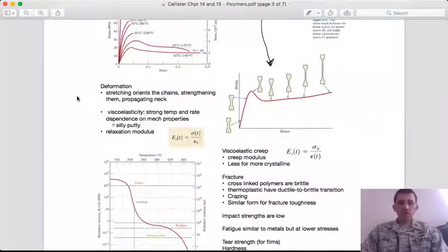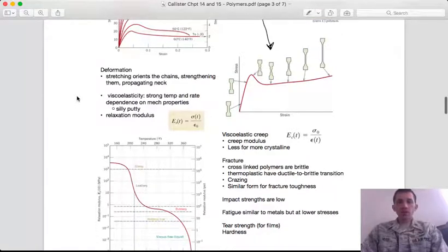And this is because, as we'll see later on, when you stretch a polymer, the sort of intertwined length of polymer chains, kind of the plate of cooked spaghetti mental model, you're pulling it and you're aligning those chains, which, like we see in crystalline regions, when the chains are aligned, the bonding between them is enhanced because you have more interactions amongst the same chain, and you're also aligning those fibers along their strong direction.